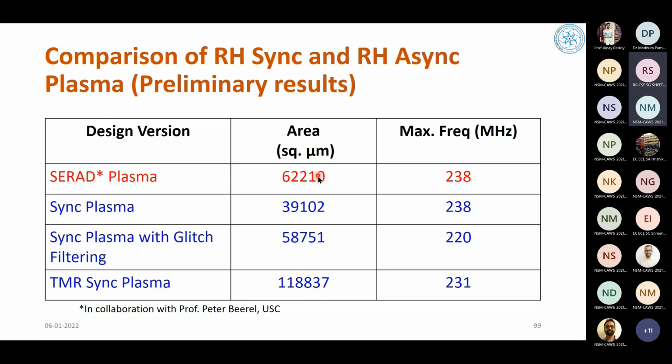Because we want to compare, what we are doing is this: in the case of Plasma, there are 3 stages, and we know that one of the stages is the slowest of the 3. To report these numbers, we have taken that stage and first found its critical path delay. Critical path delay is the max delay, which is what DC gives us. To this we have added the delay of the controller, which is independently synthesized in Cadence.